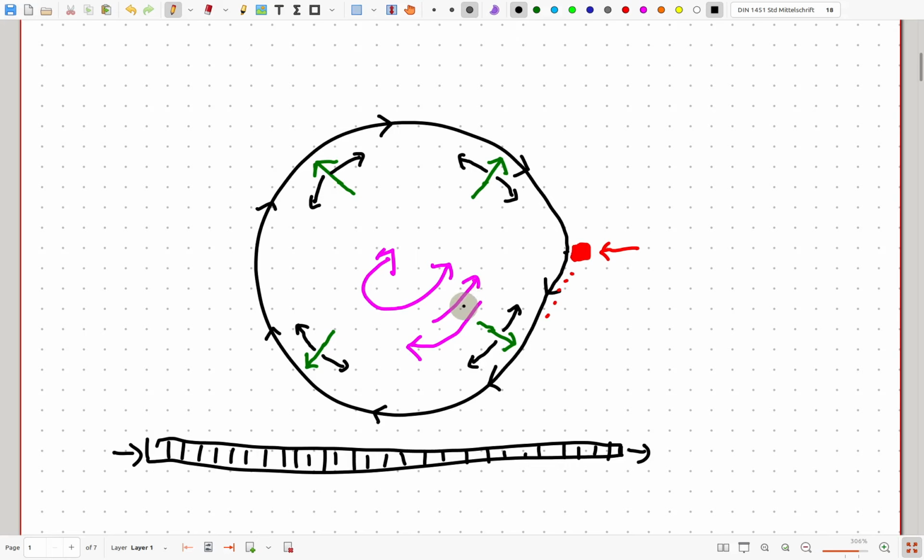Now, there are two ways of doing a buffer like this. If you've got a fixed length of buffer, that's very easy. You just choose your sample rate for your audio system and you make the buffer an appropriate multiple of that, and that's the length of your buffer. If, as in this case, we want to have a control that varies the length of the buffer, and that can happen while the card is running, then we've got a couple of options.